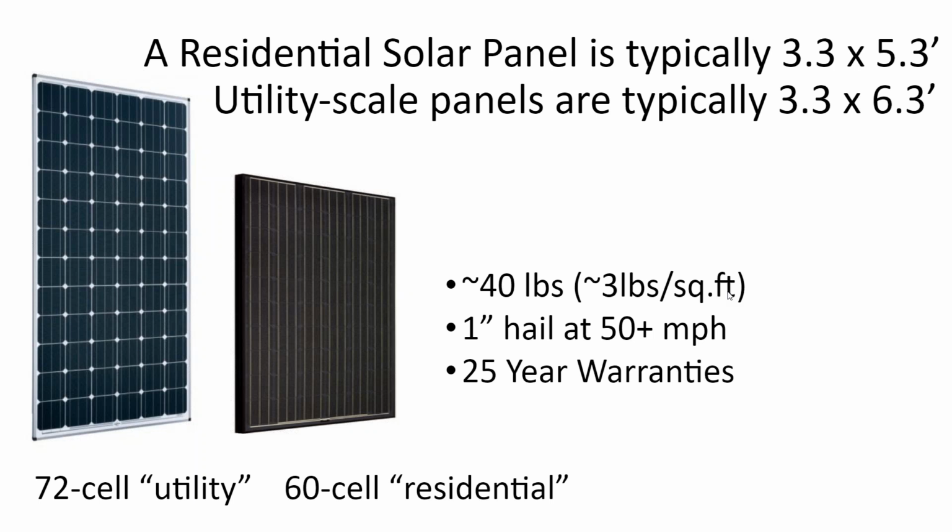That's not to say that array shouldn't be looked at over the years to come because it's not like panels are bulletproof. You should not walk on them. They are fragile. And the thing about them is, while they are rated for outdoor environments, which means they are very tough, that can mislead the installer into a false sense that they are bricks or concrete blocks or pieces of plywood, that you can be too rough with.